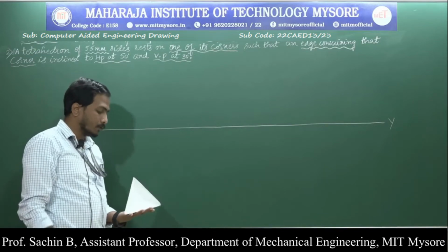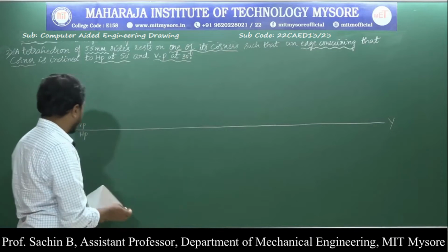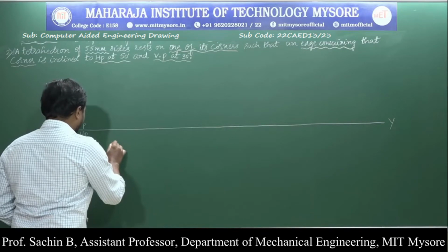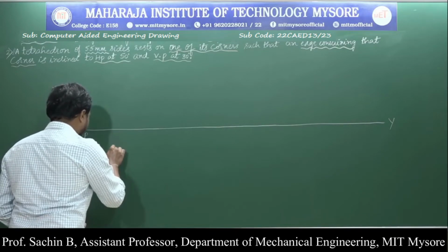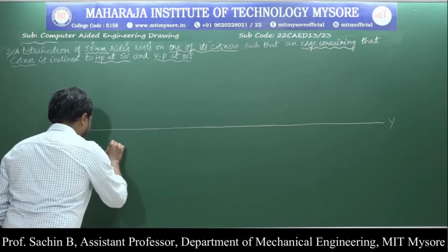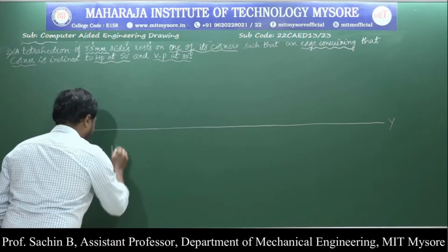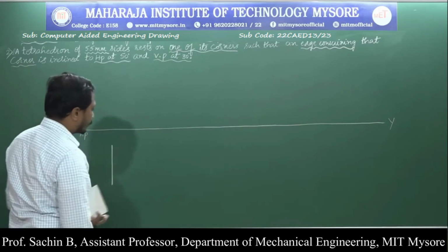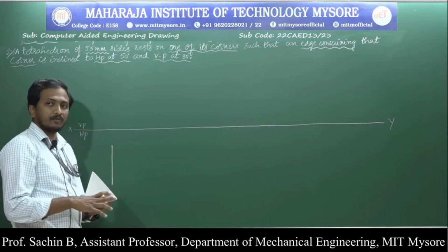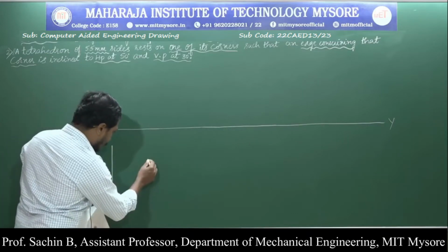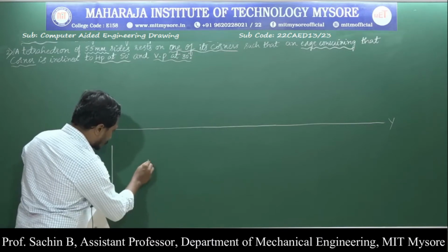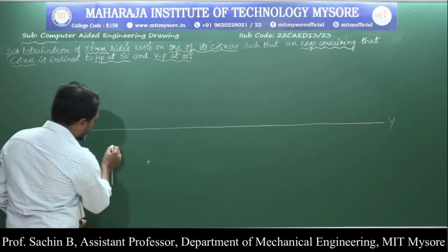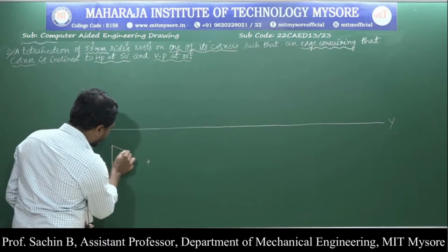If I look from the top view, the object will look like a triangle. First I will draw the dimension of 55 mm, for a tetrahedron of edge length 55 mm. Next, with the help of the compass, I measure the 55 mm length. From this corner, I cut the arc. Again, from this corner, I intersect this arc. I have marked the 55 mm edge length. Next, with the compass, I draw the arc. Next I will join the points.